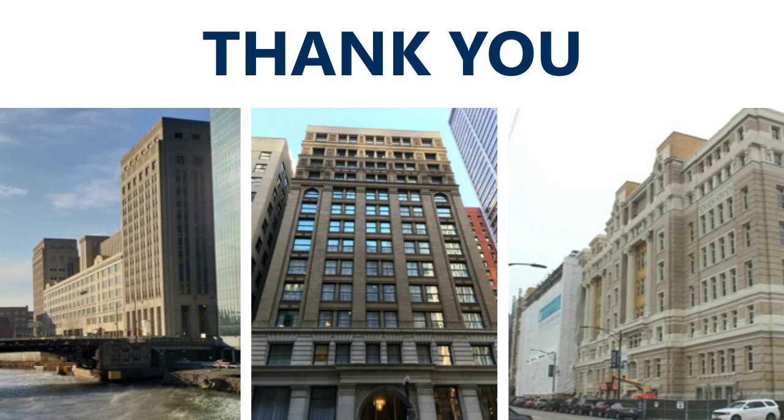One thing along those lines is really having the scope documents and understanding that the scope may shift. Sometimes repairs that may not be as necessary in the early stage become the contingency for repairs that are needed more immediately. As Matt said, the terracotta contingency is probably higher than most other masonry materials, and 20% is not unheard of in those instances. Sometimes people think that's a little bit crazy, but it's pretty typical to see 20% or more.